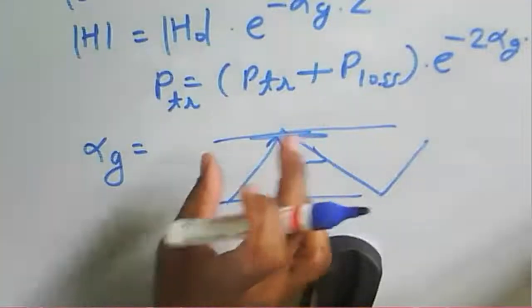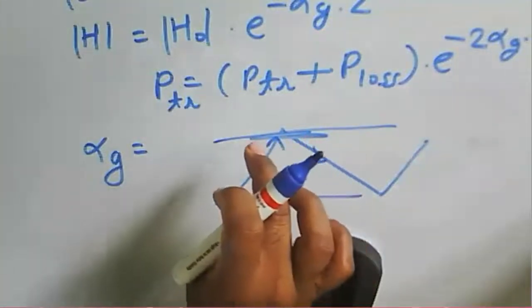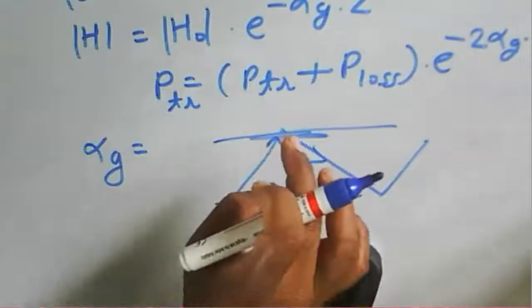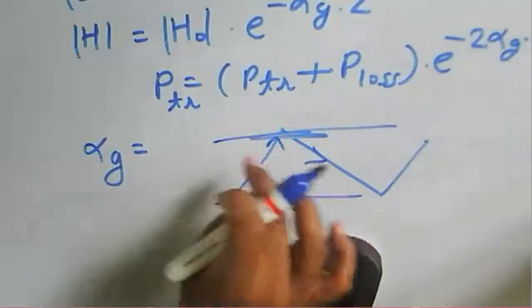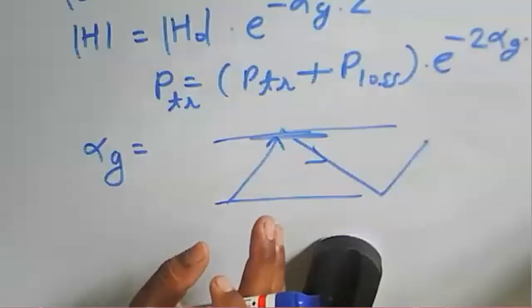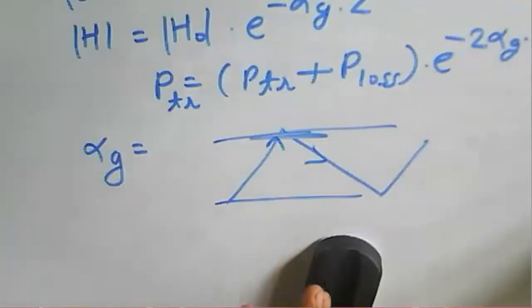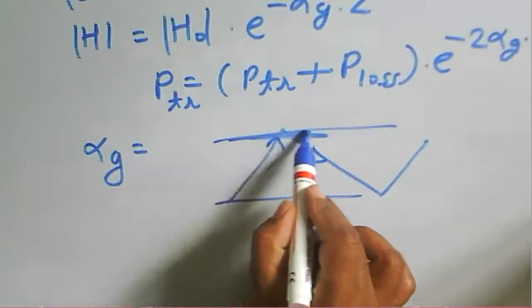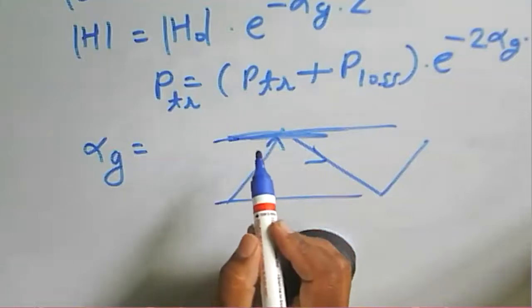So that we get based on what the conducting wall surface is. From that we can calculate the skin depth for this given conducting wall, meaning how your wave propagates inside this particular wall. That's why we should know what the surface resistance is for this particular wall.